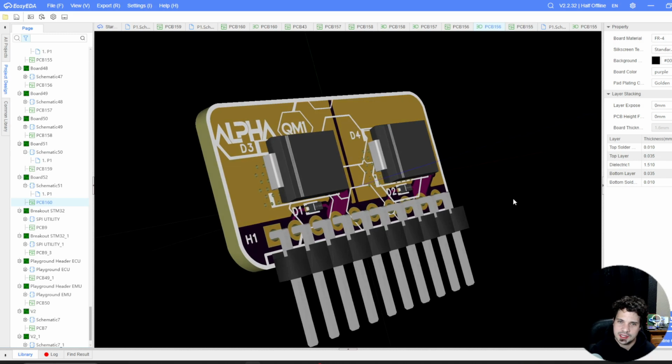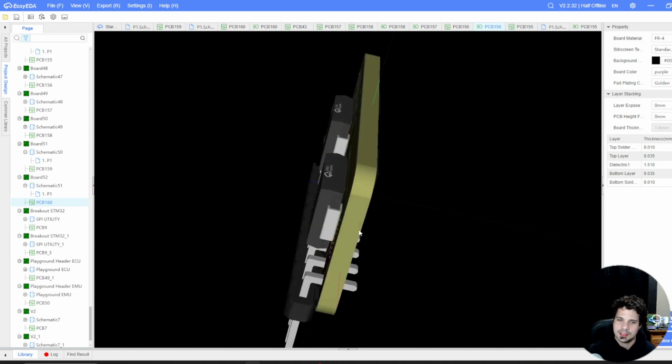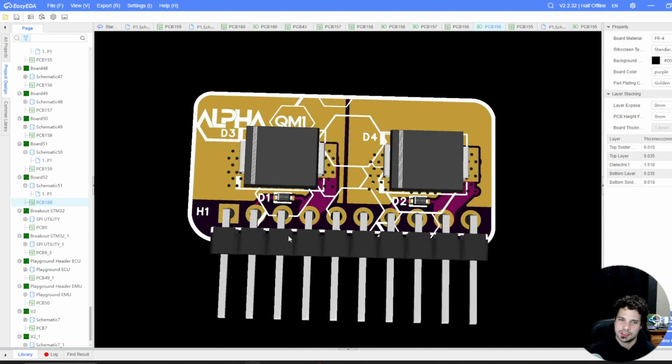So with that being said, I've actually bridged those same traces on my QM1 IC and I bridged the separate traces on my QM2 IC. The reason for this is it offers lower impedance and direct connection to the way that the ECU is actually trying to make the hardware work instead of forcing the hardware to work. So my replacement hardware is actually more in line with what the ECU is expecting versus what it is trying to make the hardware do.